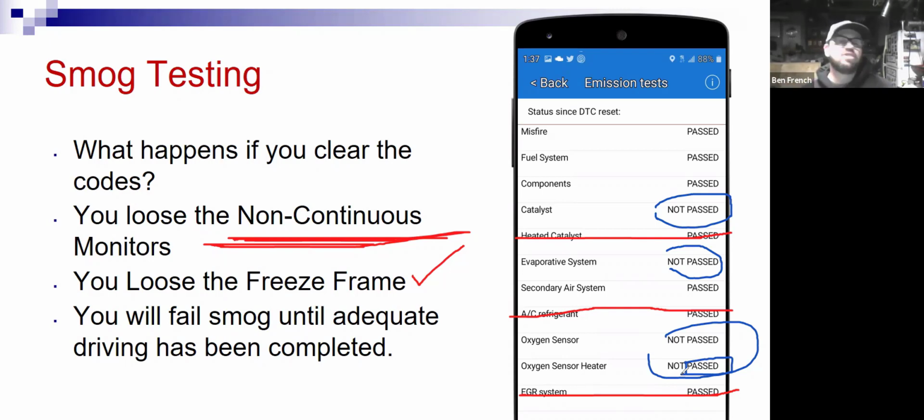In fact, cars that are newer than 2002 in the state of California, well, we don't even measure the tailpipe emissions anymore. We're totally relying on our visual inspection and this feature of the OBD system with the thought that, hey, if it's passing all the monitors, the emissions of the vehicle have to be low. So this is crucial.